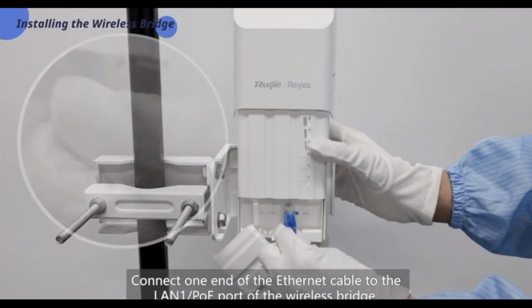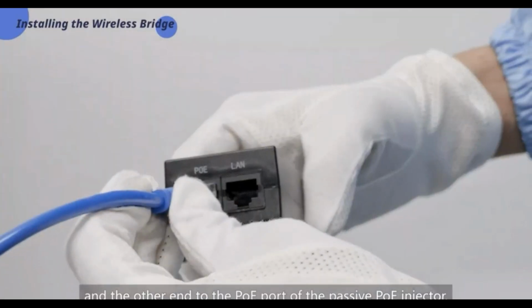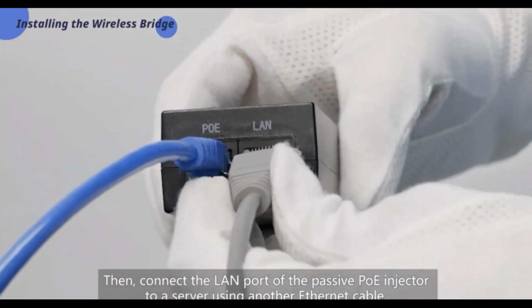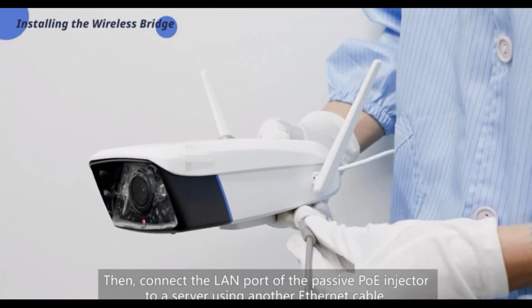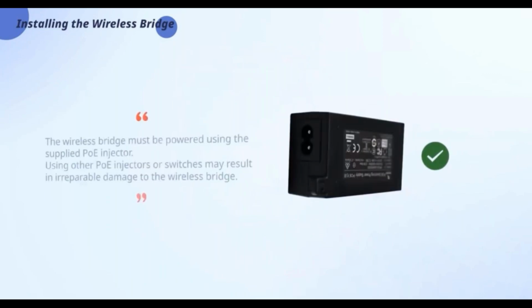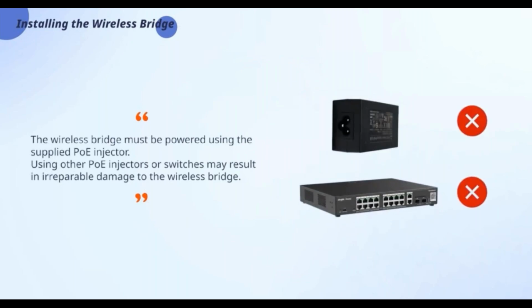Connect one end of the Ethernet cable to the LAN 1 PoE port of the wireless bridge, and the other end to the PoE port of the passive PoE injector. Then, connect the LAN port of the passive PoE injector to a server using another Ethernet cable. Finally, plug the power cord into a 220V power socket for power supply. The wireless bridge must be powered using the supplied PoE injector. Using other PoE injectors or switches may result in irreparable damage to the wireless bridge.